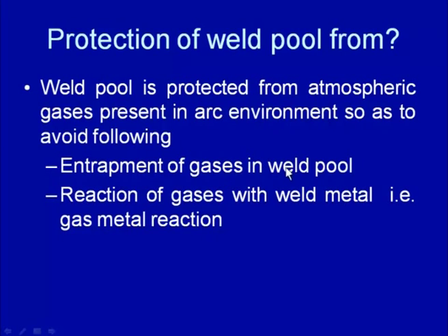Further, these gases can also react with the molten weld metal, leading to undesirable reactions in the form of gas metal reactions, which may result in the formation of oxides, nitrides, and the dissolution of these gases in the molten metal, which can produce porosity and inclusions.